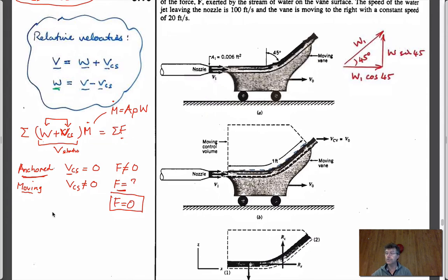And I guess we also talked about the fact that we could calculate the power that came out of this merely as the product of the static velocity multiplied by the force. So this static velocity, in this case, the velocity to a static observer relative to the force that's applied. So force is in newtons, static velocity is in meters per second, so power is in units of Newton meters per second. A Newton meter is work, and work per unit time is power in watts.